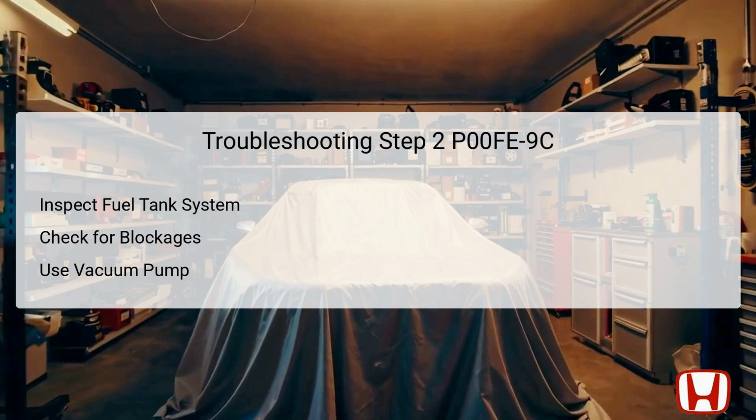In the second troubleshooting step, focus on the fuel tank system. First, insert an emergency fuel funnel into the fuel filler neck. This funnel is typically stored beneath the cargo floor lid for easy access. Disconnect the fuel vent tube from the EVAP canister to isolate the system for testing. Connect a vacuum pump or gauge to the vent tube. By applying pressure, you can test the integrity of the fuel tank system.